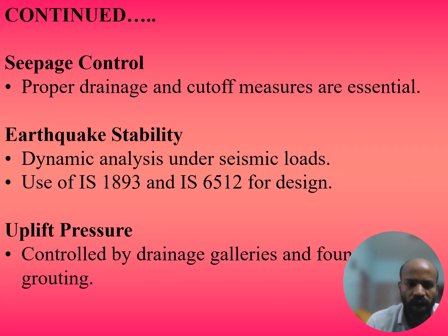Next, seepage control. Seepage can be controlled by providing proper drainage and cutoff measures. Next, earthquake stability. In order to make dam earthquake resistant, dynamic analysis under seismic loads has to be done. Indian codes IS 1893 and IS 6512 provide important specifications to be followed for doing dynamic analysis under seismic loads. Next, uplift pressure. Uplift pressure can be controlled by providing drainage galleries and foundation grouting.